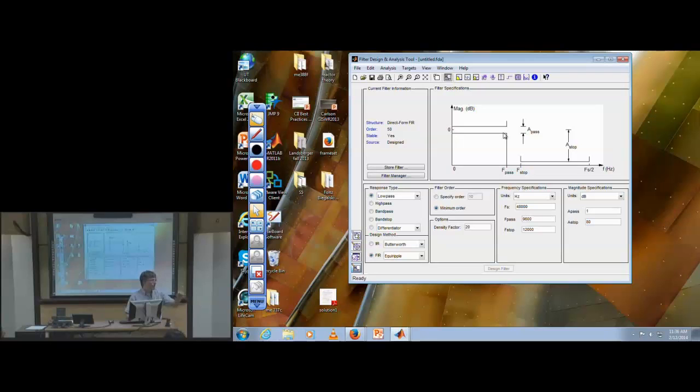It's going to alternate, and we want to keep it in that small stretch so that those frequencies appear to have been passed. So in audio, they sound like they've been passed. In imaging, they look like they've been passed. If you let that variability grow too big, then you're going to be amplifying some and attenuating the others, and you're going to hear a difference. So we're going to tie this into quantization later, that it does relate back to quantization that you're doing.